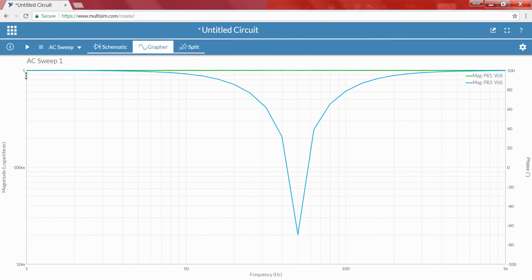But now, if you see at a frequency of somewhere around 50 hertz, the magnitude is very small, right, and suddenly, just above 50 hertz, it starts rising. So, when you see the valley, it is very narrow, which is why this is called a narrow band filter too. Very narrowly we can cut down one particular frequency.